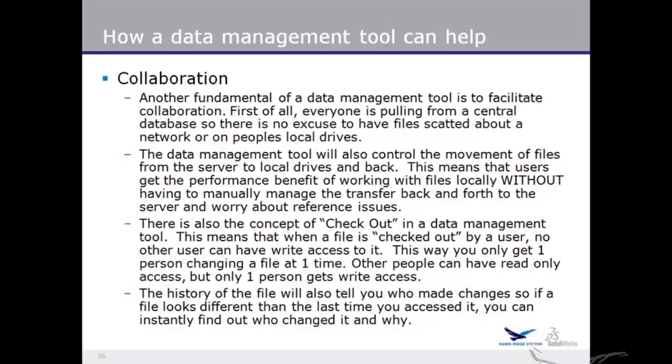What the data management tool also has is this concept of checkout. Basically, when a user checks a file out, they are taking responsibility for that file. So when I have a file checked out, nobody else can have write access to that file. Until I check that file in, nobody else can make changes. Sure, I could check the file in and somebody else could grab it and make changes, but the great thing about that is I've got two versions now. So if their changes were unacceptable, we can roll back to my changes and ditch what they did.